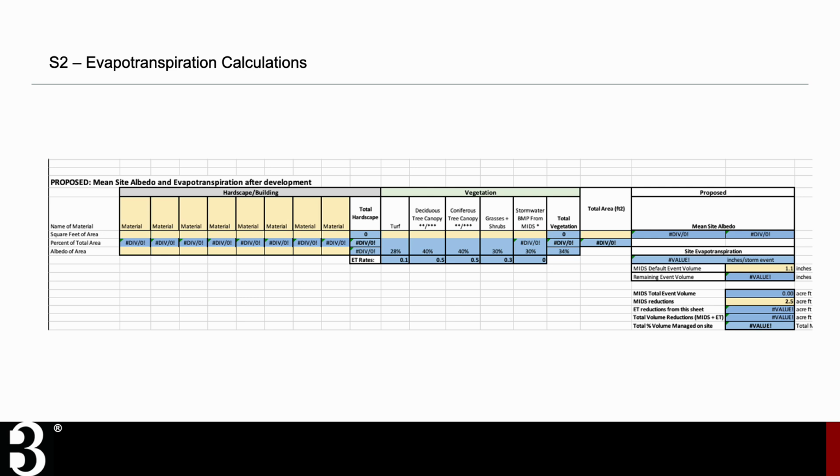So you should start with your total site area and then use the different relative albedo numbers that are in the list embedded in the tool to fill out the chart. Make sure that your overall site percentage is 100 when you think you're done. And to do that, only one material can be used for each separate zone of the site.